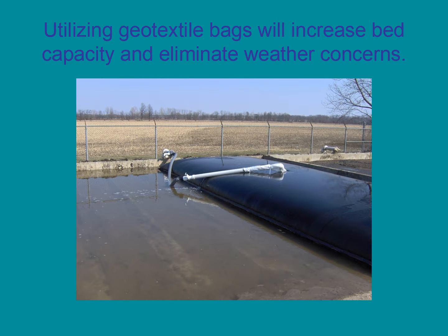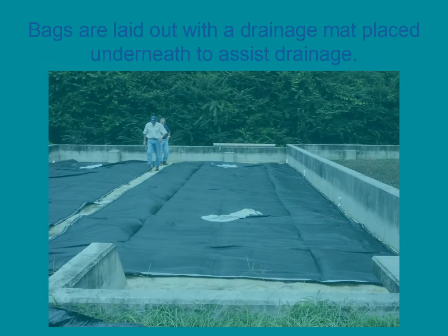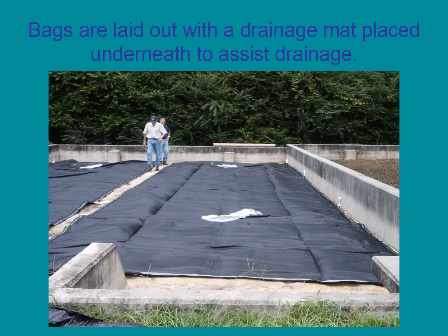Utilizing geotextile bags on the beds will greatly increase the capacity of the bed and make the bed an all-weather tool. The bags are laid out over the bed and a drainage mat placed underneath.